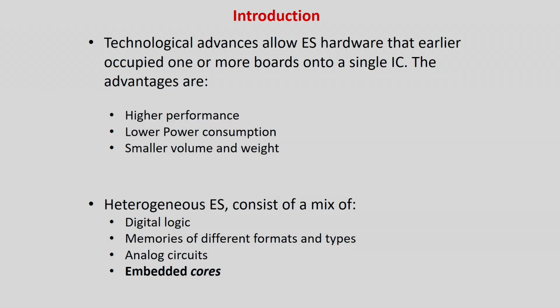Why has the concept come? Because one vendor cannot be an expert in manufacturing or designing all kinds of IP cores. One can be more dedicated towards graphic processing, one towards designing processors, one vendor can be more expert in designing on-chip memories and so forth. So if you have to design an entire embedded system hardware, you will design some of the modules, procure other modules directly from a vendor who is an expert in that, put them together on a single die and give it to fabrication.